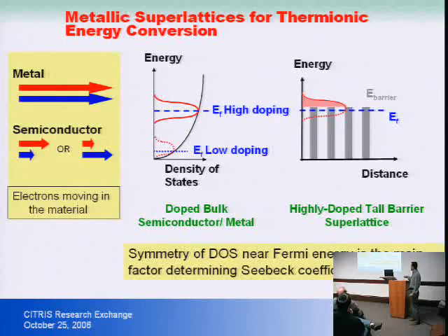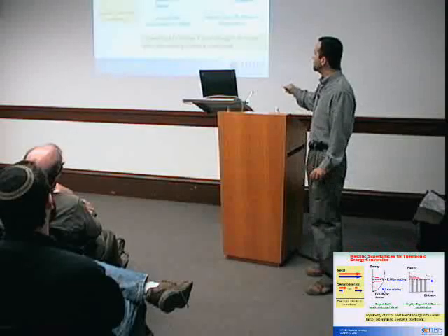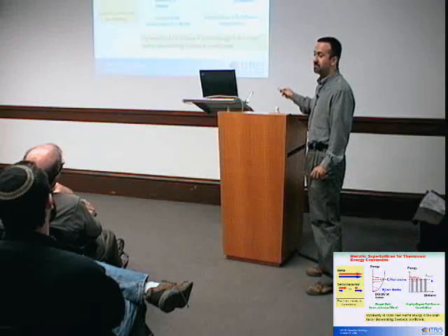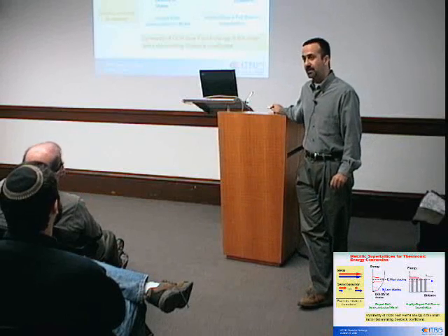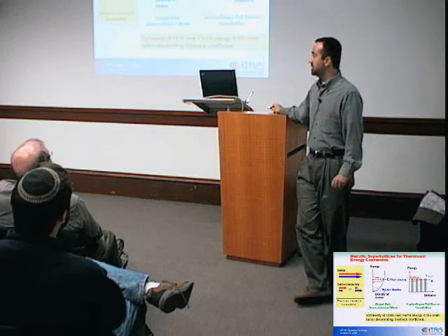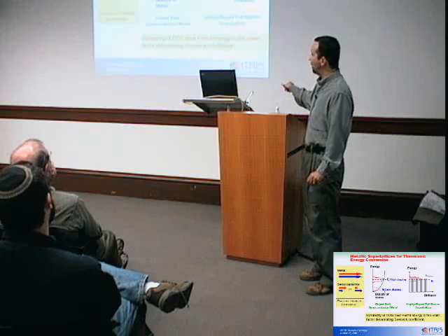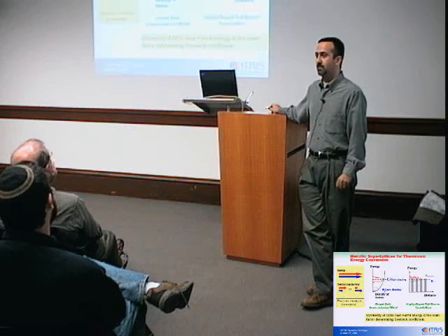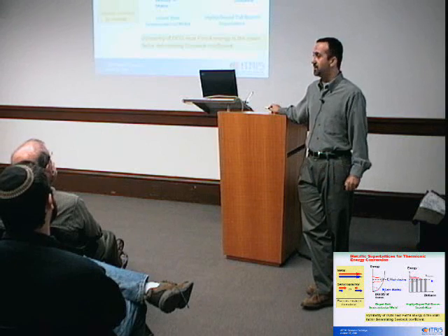In a semiconductor, when you apply a bias, hot and cold electrons move by different amount. And this difference is the exact definition of the Seebeck coefficient. And this is why this works. And the picture here shows the density of states and the Fermi energy. So for those who have seen it, it's the same figure. But that's basically what is behind why metals are good electrical conductors. Lots of electrons move, but they don't have good Peltier effect. So what we could do is basically make a metal and then block one of the electrons. That's basically creating speed bumps for some of the electrons.